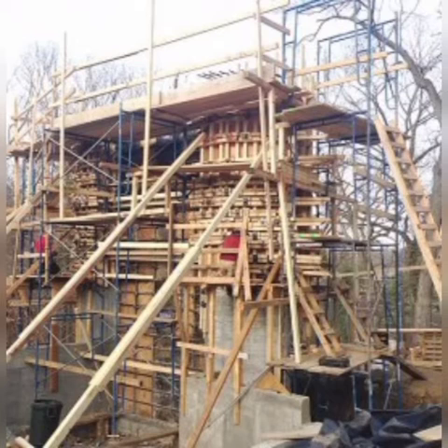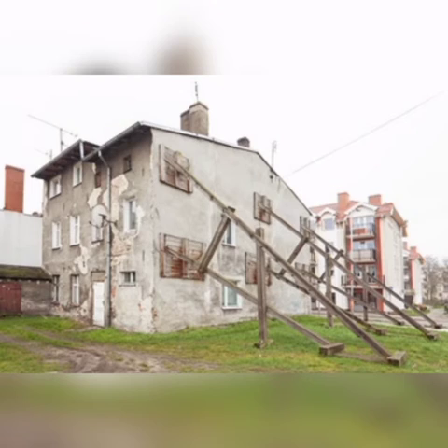Shoring should be designed according to the load and the duration of the load. It can be internal or external depending on the case of the structure. There is no time limit to which the shoring has to be kept. It may range from weeks to years depending on the case of the structure.